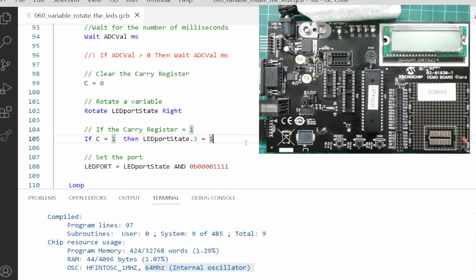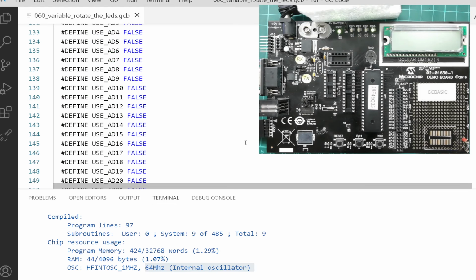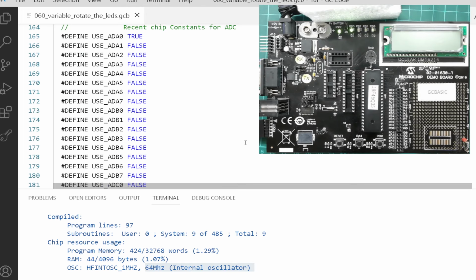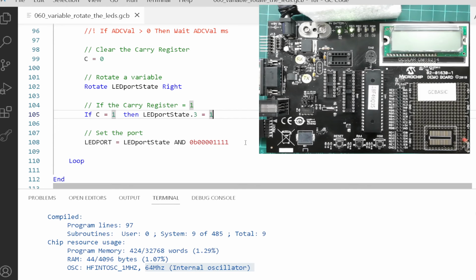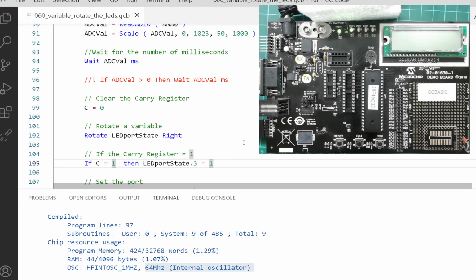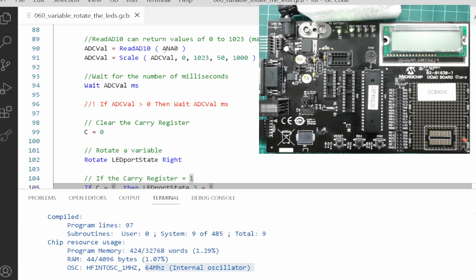We've got at the bottom of this code the optimization code that I showed you yesterday in the previous tutorial. So it has been optimized. It's sort of throwing some of the code out. Now, you can do an ADC read in assembly. You can do it lots of different ways. This is a utility. Think of this as being a utility method. If you wanted the fastest, you could just take the code that we've generated and get rid of the rest, okay? Just do the register changes. The same with scale. Scale is a utility.